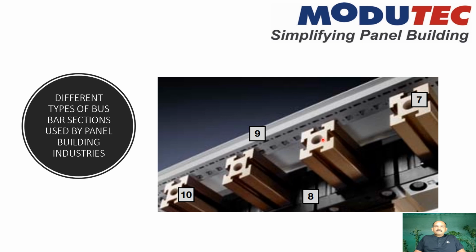This is a modular busbar structure. Here we need not drill. We just need to insert the nuts inside, and we can connect the jointing without any drilling on the main busbar. Only the interconnection busbars have to be drilled, and they are taken through the slots provided on all the busbars. In any direction, top, side, and bottom, we can connect the interconnections. This is also a very good thing.